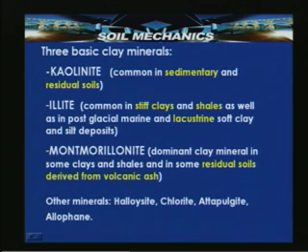Kaolinite is generally prevalent in sedimentary and residual soils. Illite is common in stiff clays and shales, as well as in the post glacial marine and lacustrine soft clay and silt deposits.